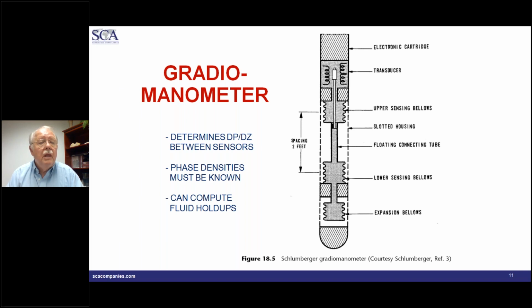How do we use this tool? Well, suppose we have a mixture of 50% water and 50% air, and it was well mixed and churned up. What would we see in terms of the bulk density? Well, we would see a bulk density contributed 50% from the water, 1 gram per cc, and 50% contribution from air, 0 grams per cc. So we would have a bulk measurement of 0.5 grams per cc. That would indicate 50% water, 50% gas, or air rather.